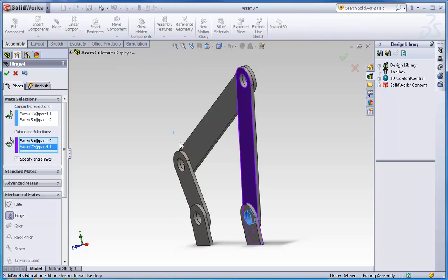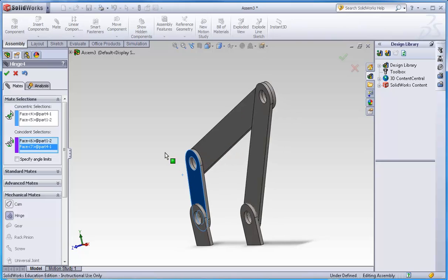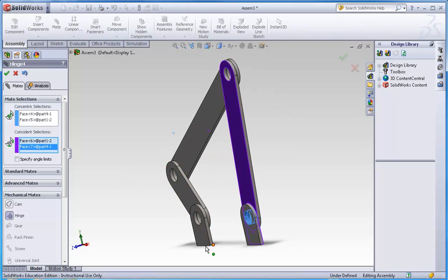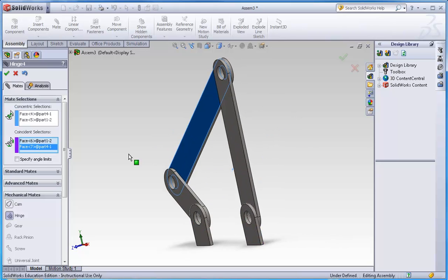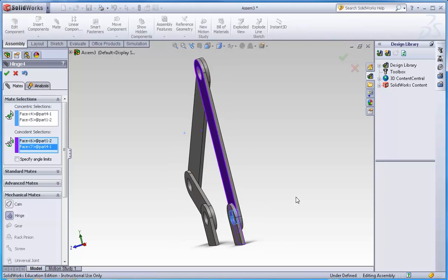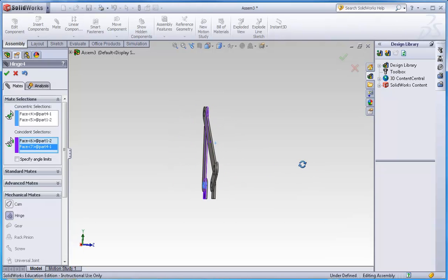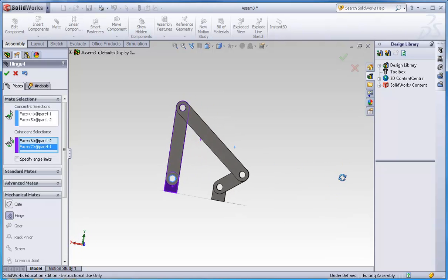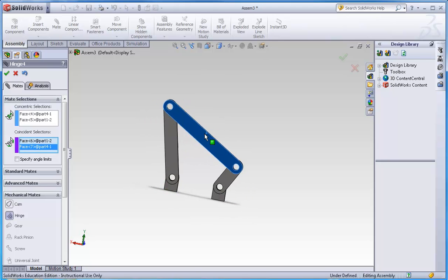Let's zoom the mechanism out and see what this thing does. This is called a four-bar mechanism because we count the ground as one link, and we get coordinated motion among all of these various links. I'm going to rotate this one around to the direction where I want to visualize it. My mouse goes a little crazy, bear with me. Okay, and so you do see, for the first time, that when we have an assembly of parts, we can in fact make that assembly move.